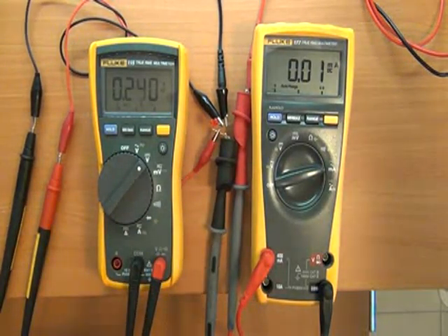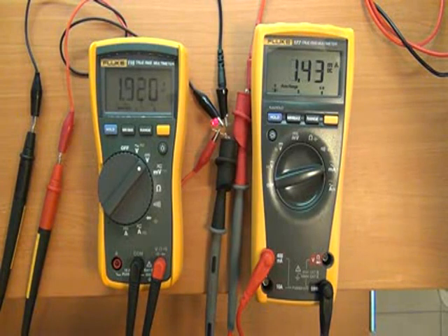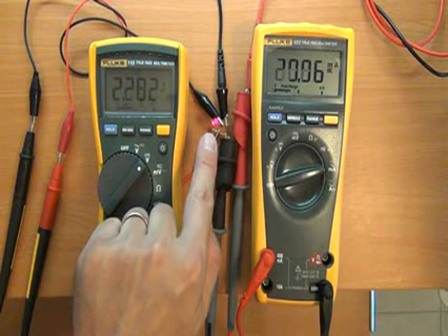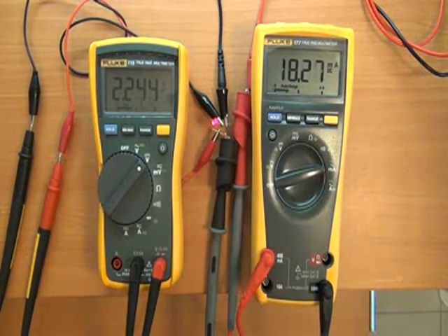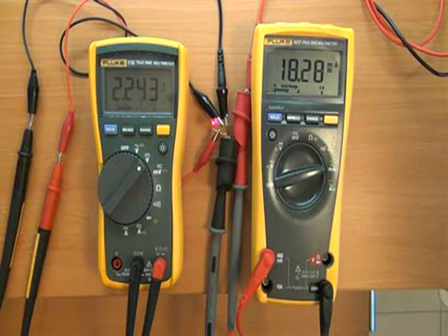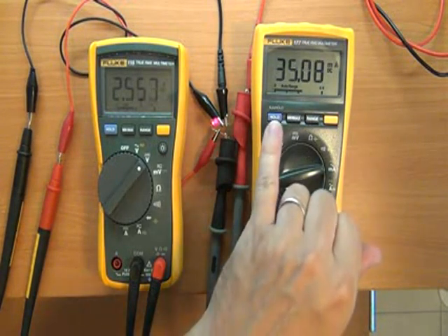Let's see when the LED does light up, you'll see the voltage. There we go. We can just see it come on there. And what are we at? About 2.2 volts. So now you're seeing basically exactly what my variable power supply is putting out. I'm going to step the voltage up until we blow the LED. Let's see what happens.